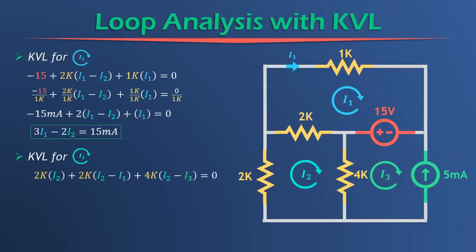Alright, so then after the 2K resistor, we hook a right here, and we meet up with our 4K resistor. What's the voltage across the 4K resistor going to be? Again, it's the same thing: its resistance times the current through it. We're in the loop I2, so I2 is in the positive direction and is positive again.